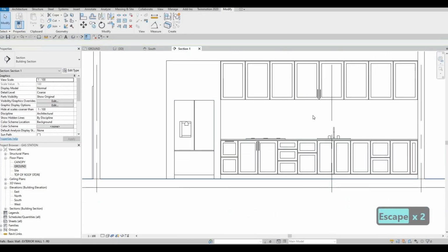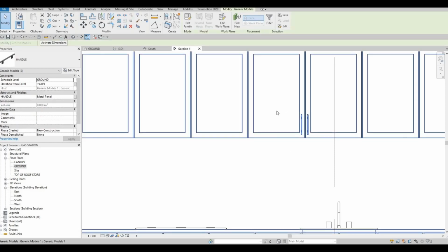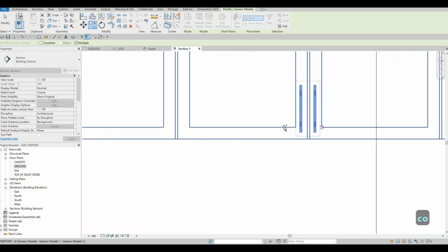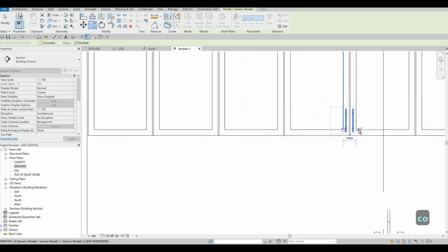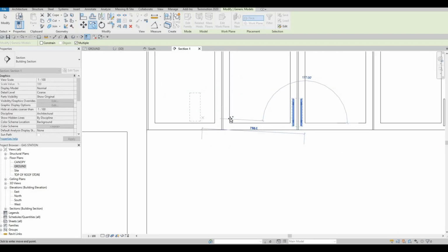So once I set all of those, what we could do is just basically hold the shift and then create a window, and then unhold the shift before you unhold the click of the mouse. After that, CO, and then here you could grab it wherever you want, but I'll grab it right here so that I will be able to replicate the location on the others.